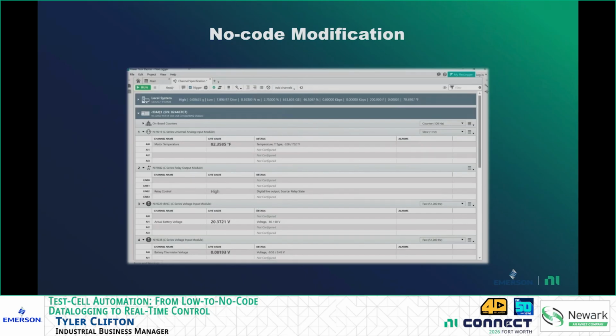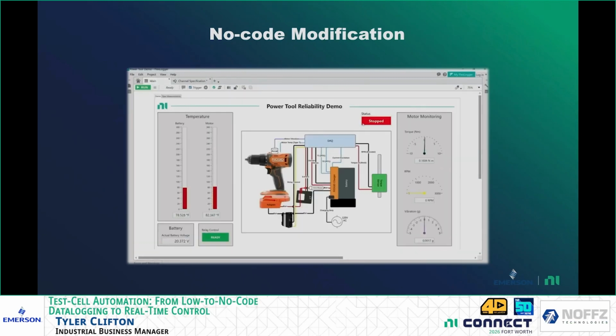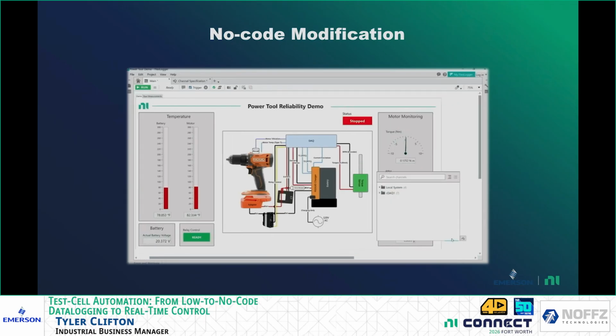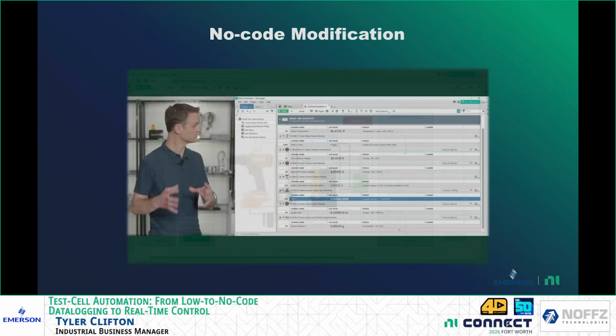So now if I want to add that to my front panel, I can just simply go in here, right click, and let's map that to an indicator, a numeric indicator. Let's look at that here. So you can see I just did RMS. I can type that in the search, add that here, and now I've got RMS acceleration.